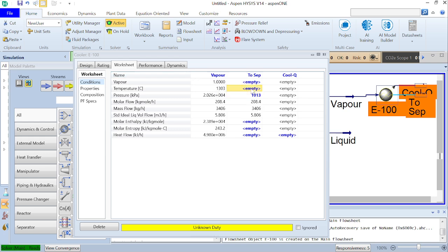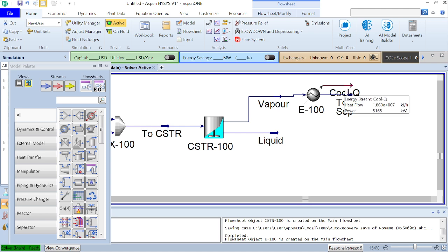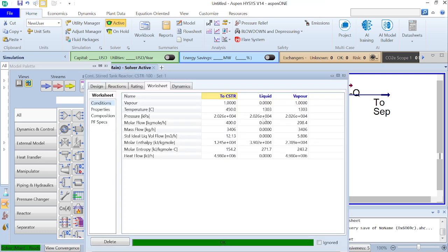And then now for us to have liquid ammonia produced, the temperature is usually below minus 33.6, so we're putting minus 33.6 here, and then at this point we have ammonia coming out from here. So let's check worksheets, composition.